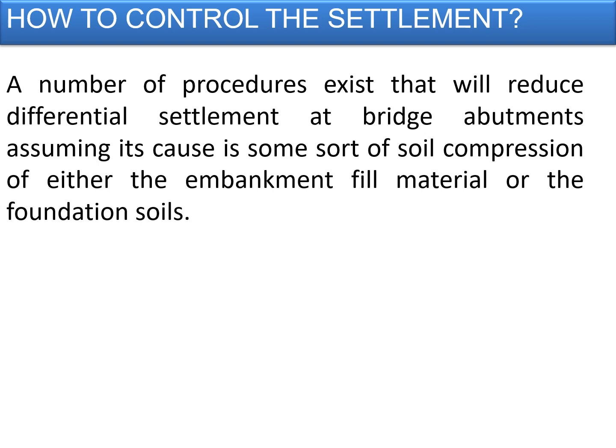A number of procedures exist that will reduce the differential settlement at bridge abutments, assuming its cause is some sort of soil compression of either the embankment fill or the foundation soils. Sometimes erosion also plays a major role as far as the settlement of the approach slabs is concerned.